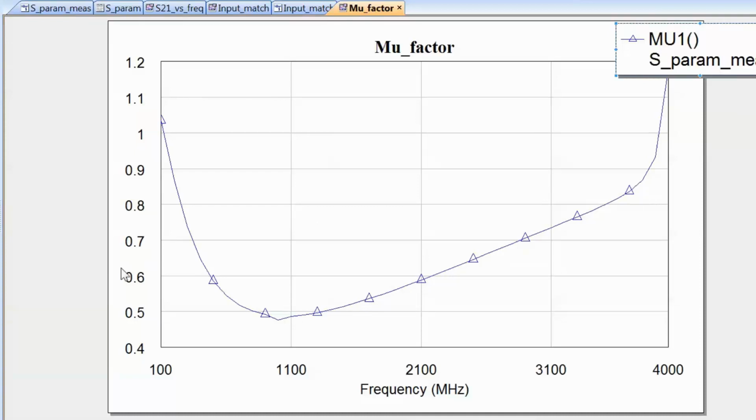And now we'll have a look at what input terminations can cause the output reflection coefficient to be greater than 1, and what output terminations can cause the input reflection coefficient to be greater than 1. And of course, because we're looking at values of impedances, we can just use the Smith chart to represent these, with very useful tools which are called stability circles.